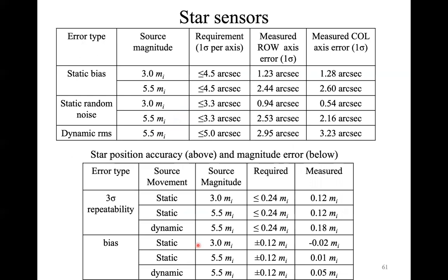The other table that I showed you is related indeed to the measurement errors. I know that these tables are not really clear, but they refer to basically a very realistic star tracker, and show you the errors that you have in your star sensors related to the magnitude of the stars. So basically at different magnitudes, the error sources are slightly different. That's the reason why you have one column that shows you the magnitude.